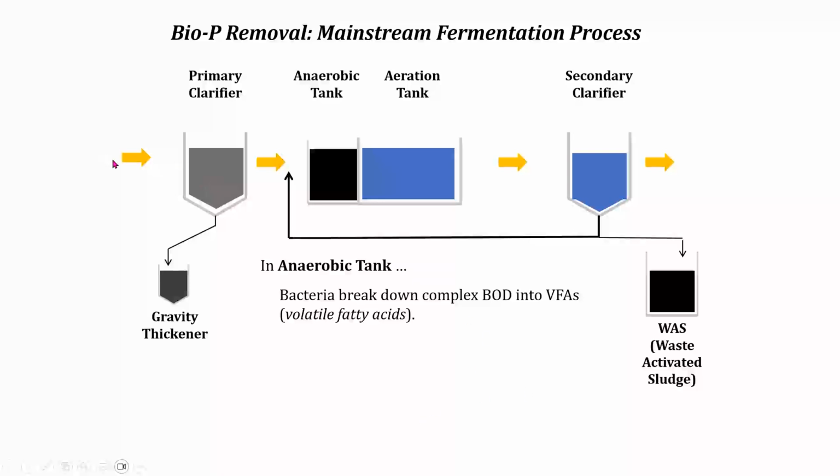show going from left to right, kind of a conventional treatment plant. Maybe has primary clarifiers with some kind of primary sludge. Maybe does not. I can't remember. Do I have that? No. So it may or may not have primary clarifiers. And frankly, for both nitrogen and phosphorus removal, as long as there's the aeration capacity, you're going to get better performance without primary clarifiers, because having enough organics, enough BOD to drive nutrient removal is often the limiting factor on a treatment plant's capability. So rather than belabor the pros and cons of primary clarifiers, I think you got my feeling